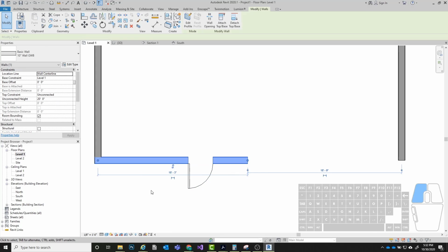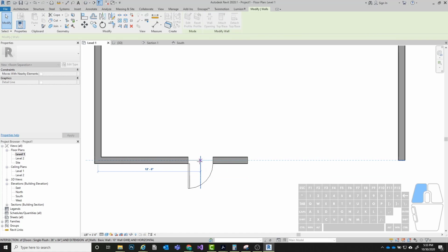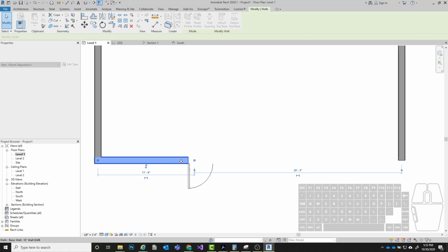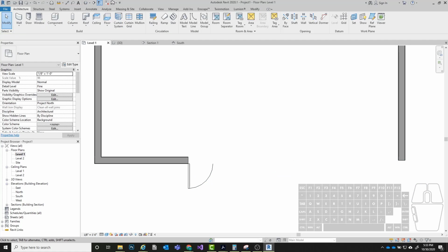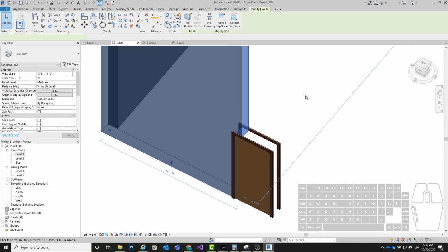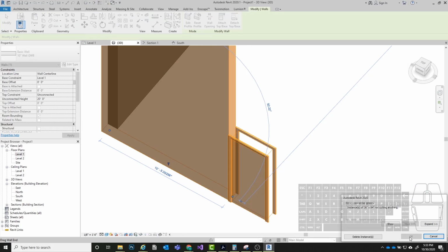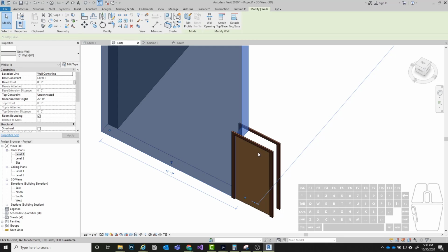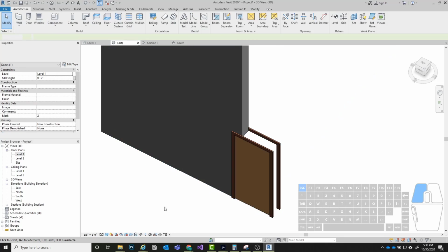Same thing with the door, and if you were to pull this back into any portion that overlaps the door, you're going to get a similar error, typically. I guess sometimes it doesn't, but usually you'll get an error if you have some sort of a conflict between where the door is placed in the wall.